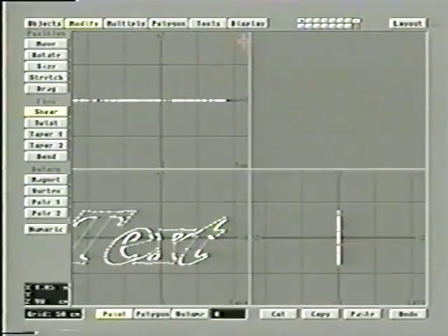And you can actually use this to manually enter settings. Again, anything you can do with the mouse, generally you can do with numeric options. In this case, because I want to eyeball it to make sure the text looks good, I use the mouse at first. But I can go in, undo it, modify my settings in numeric, and then just apply them, and it will automatically do what I say. And you'll see that, especially when we get into some of the features like bend, for instance. Just a principle there. Now, let's go back to our cube